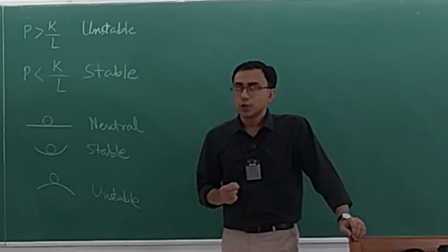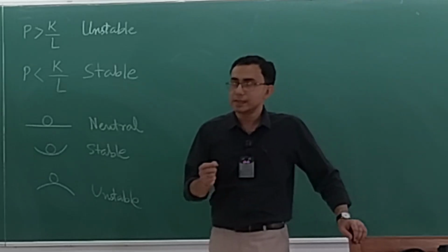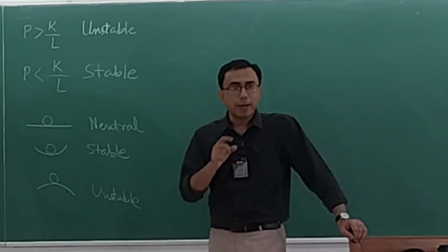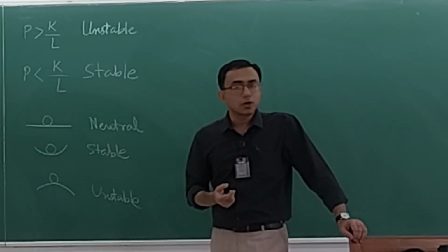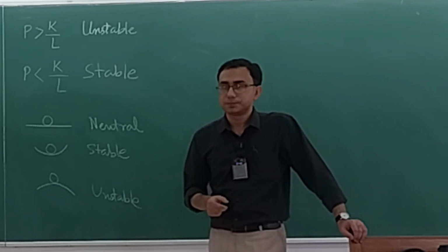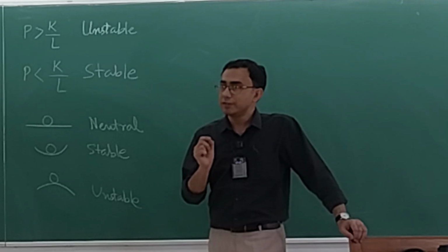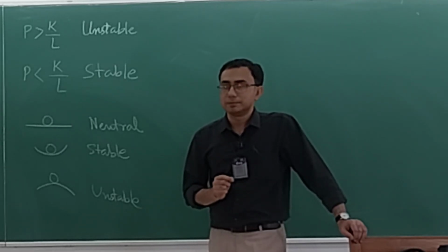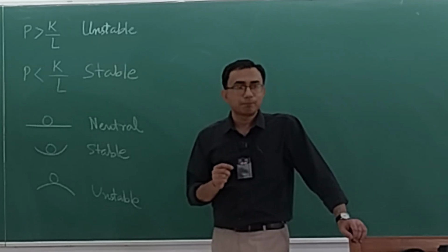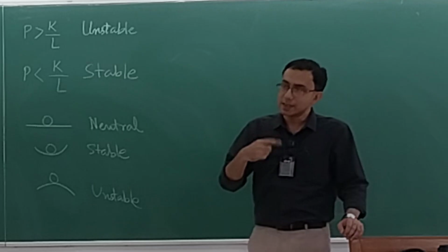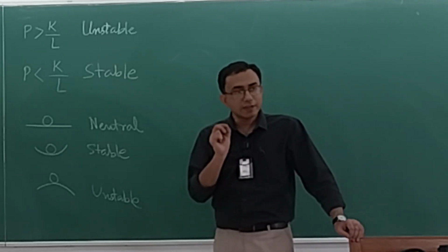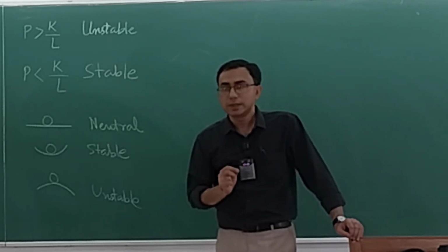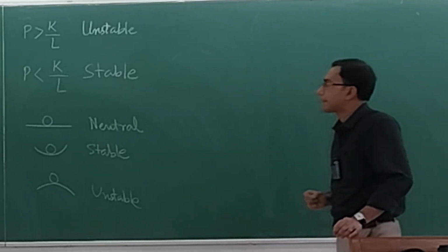Maybe you remember that there is a great significance for pipe flow with the Reynolds number of approximately 2000. Please be very careful about that. Whether it transitions or it doesn't transition is a very, very subtle concept associated with it. Please look it up.